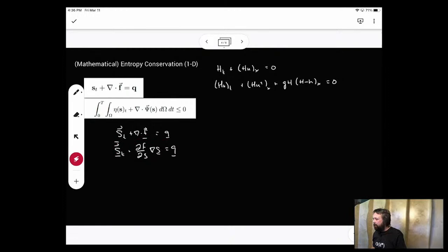It makes at least deriving the kinetic energy conservation very, very simple. So we're going to do this. We're going to look at creating the advective form for the momentum equation, and then looking at the average of the advective form with the conservative form actually gives us what's called skew symmetric, and you'll see a lot of stuff just drop out real nice when we go through and essentially multiply by the velocity field to get us the kinetic energy.